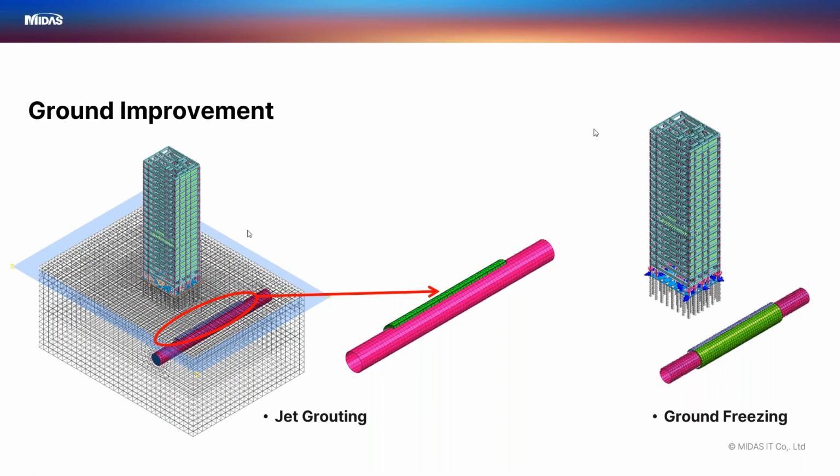Now, some of you may be familiar with the collapse of a diaphragm wall during tunneling in Cologne, Germany. What happened was that along the diaphragm wall, they were constantly dewatering the groundwater. They were reducing the groundwater level to ensure that the seepage remained at the absolute minimum.